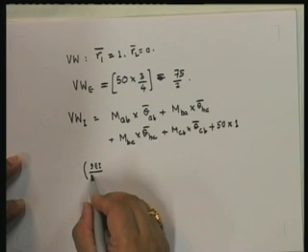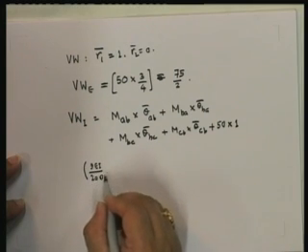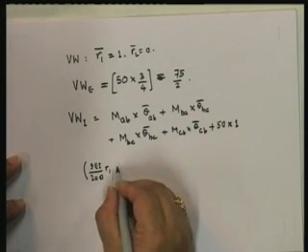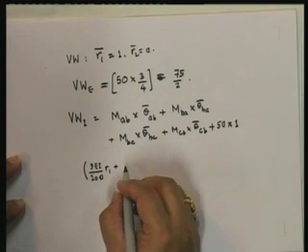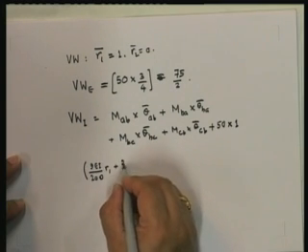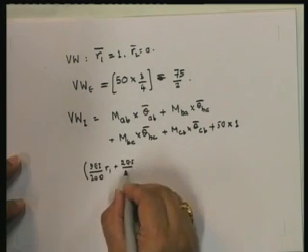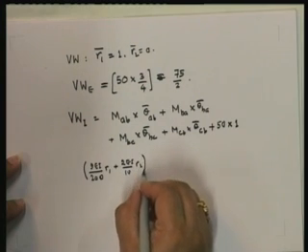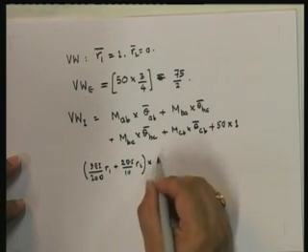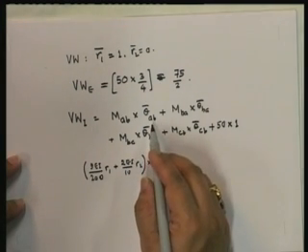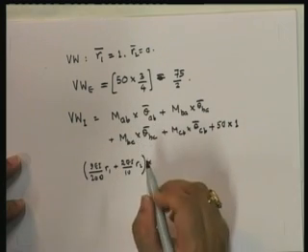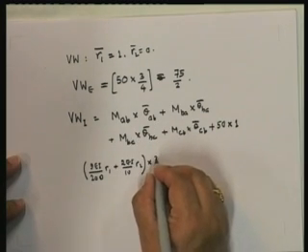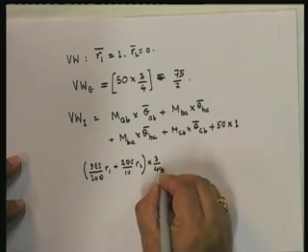9 EI upon 200 R1 plus 2 EI upon 10 R2, multiplied by theta bar AB in terms of R1, which is equal to 3 by 40.